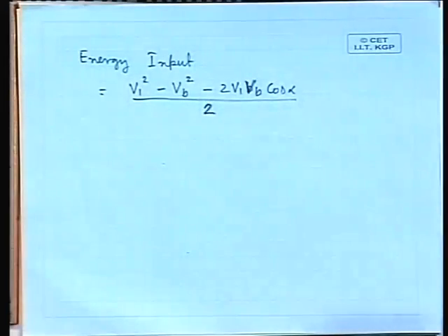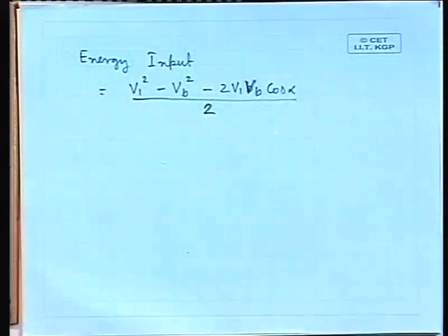These two we want to have in all our expressions, and also we want to have one angle, that is the inlet nozzle angle, or nozzle angle. So, that is alpha. That is why, replacing all the other velocity components, I have given the expression in terms of V1, Vb, alpha, etc. Now, with this, what can one do?